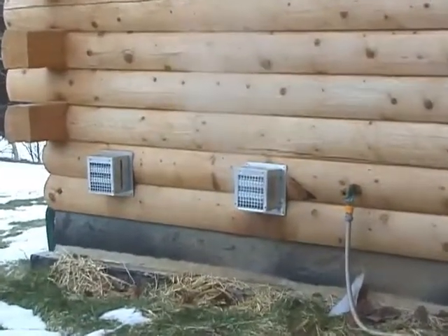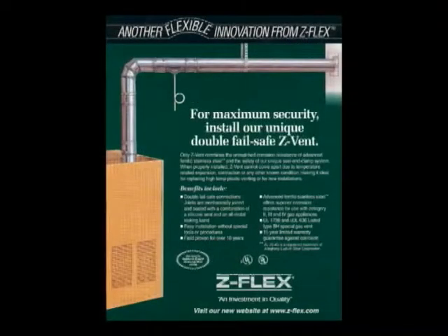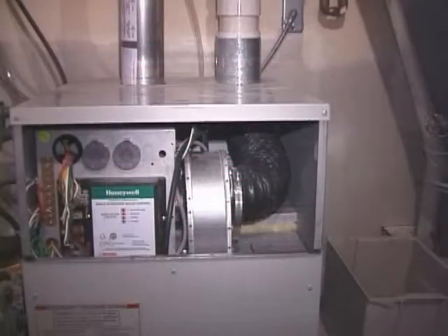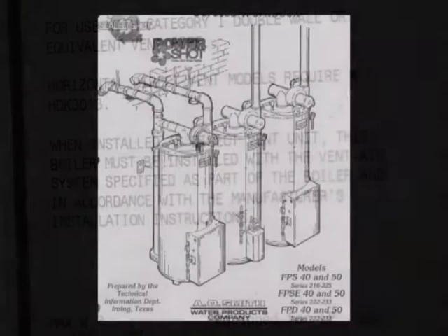As we described earlier, some Category 1 appliances may be converted to a Category 3 appliance if allowed by the manufacturer and if the appropriate venting materials are used as described by their special venting options. However, the requirements to do so are very specific in that you are now relying on a relatively weak positive pressure that is established by the inducer fan in the appliance. The requirements for doing this are very specific and the manufacturer's directions should be followed exactly.